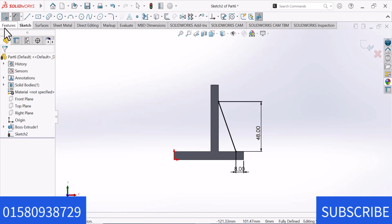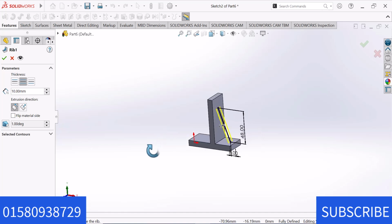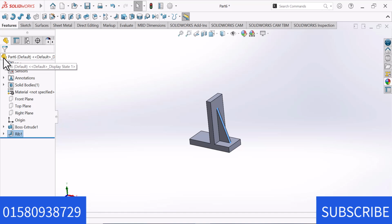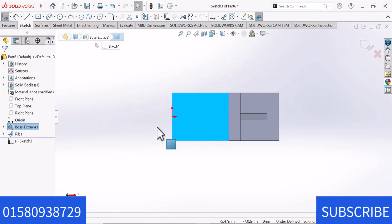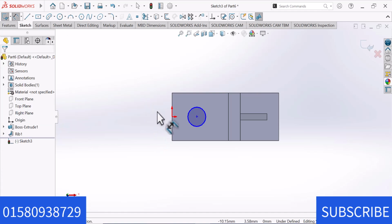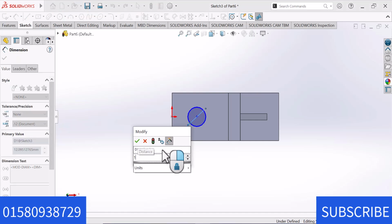Okay, now go to Feature and select Rib. Now give the value here 4 from mid plane. Okay. Now go to this face and sketch. Now draw the circle here. Now give the circle value 19.